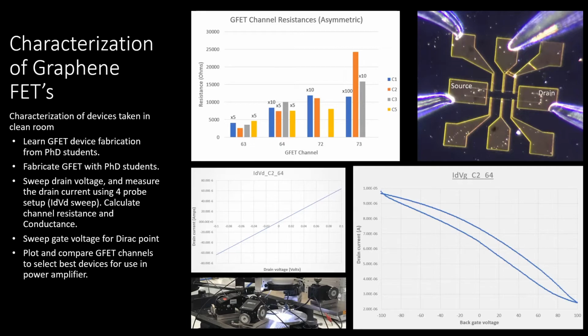Comparing the different devices is important, as being able to detect patterns may lead to improvements to the fabrication process that could increase the yield. By looking at our resistance comparison graphs, the graphene channels between the 3rd and 6th contact pad were on average better than the other channels. This may merit investigation if this pattern continues to emerge during further testing.